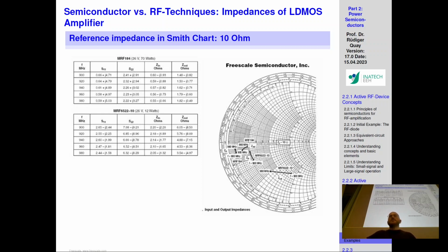It has to be willing to accept that, and a low amount has to be reflected back. And in order to do that, you have a Smith chart. I believe you've seen a Smith chart beforehand, where you're plotting the complex impedance points, and you have constant inductive lines and constant capacitive lines, where your resistance remains the same, but the imaginary part differs in terms of how much inductive and how much capacitive components you'll have.